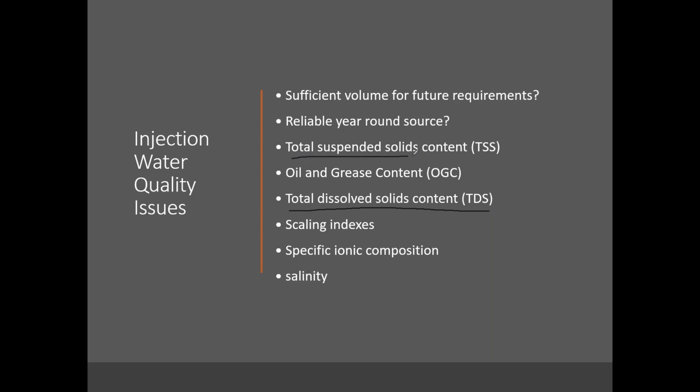The second common thing is total suspended solids. The next thing is a specific ionic composition. In the ionic composition, technically the presence of iron should be very low. And one thing which has not been mentioned is the presence of oxygen.